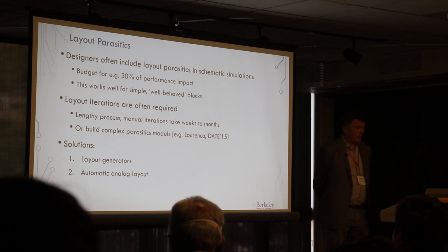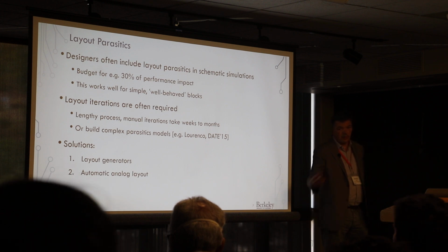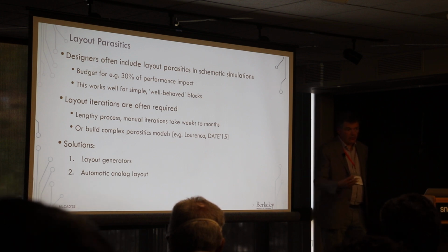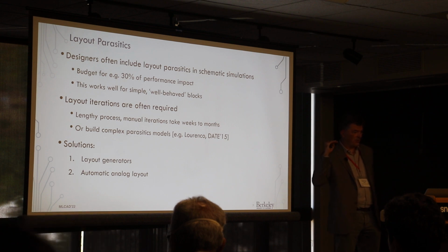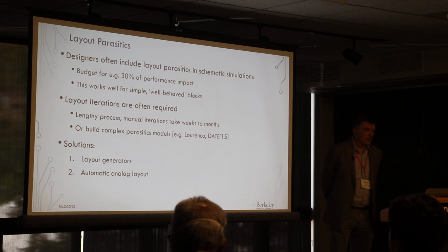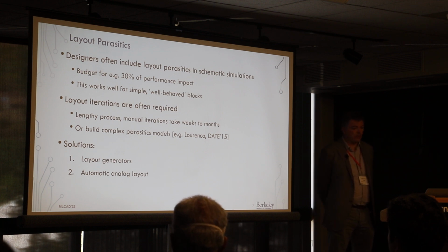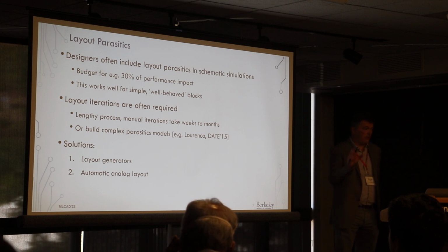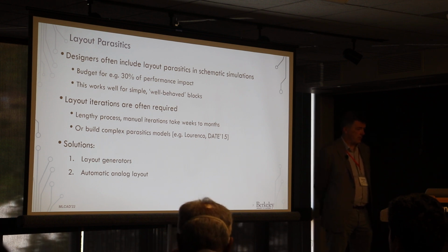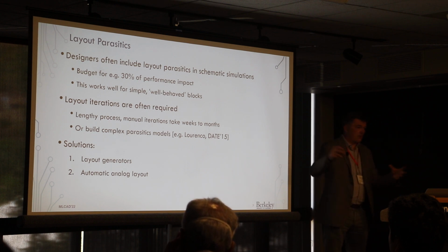So, coming up with a real impact of layout parasitics is a lengthy process. It will change the performance by more than the few percent that we can optimize things to based on schematic. There has been a trend in the academic community to build relatively complex parasitics models, and people in the industry have done that. They do have models for a particular process that try to stretch over multiple designs, but that's really difficult to maintain. It's very domain specific.